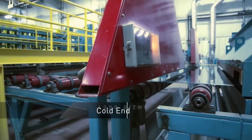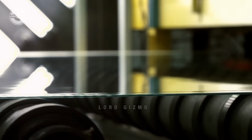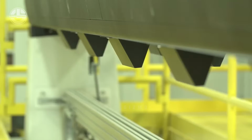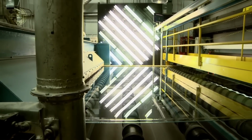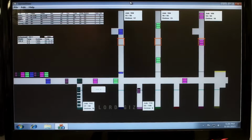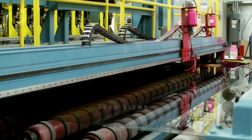In the US, Cardinal FG Company produces 600 tons of float glass every day. From the main furnace to the cold end, they process 20 miles of glass ribbon and use advanced technologies to make their product defectless. Cameras detect uniformity in the glass, lasers point out any anomalies in the edge of the glass, and experts do manual inspection. If any defect is detected, that portion of the glass ribbon is automatically marked and later cut out.